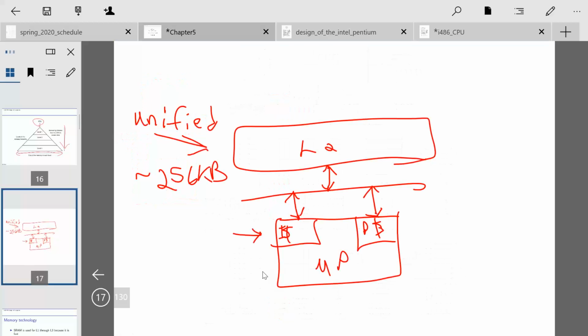Now, ARM also has an M series, which is their microcontroller base, which are your embedded ones, and those do not follow a typical memory hierarchy. So that's why I really don't use them as too much of an example in this chapter, although I will provide little anecdotes about how they do things differently. Like I mentioned, in a microcontroller, your last level memory may actually be a flash device, which is pretty slow. But microcontrollers are slow anyway, and so with the cache, it helps where you can actually execute out of the flash device.